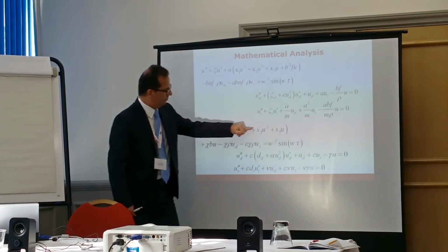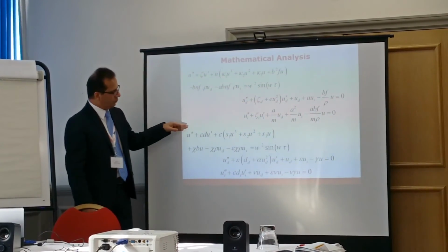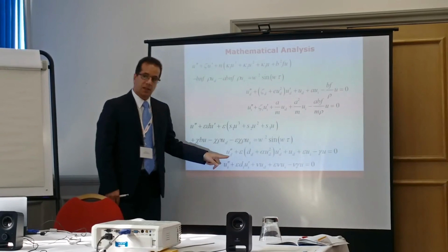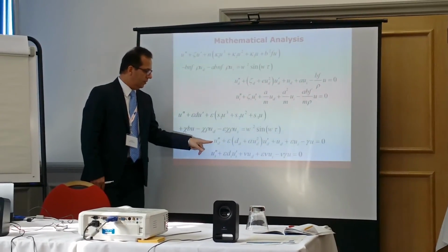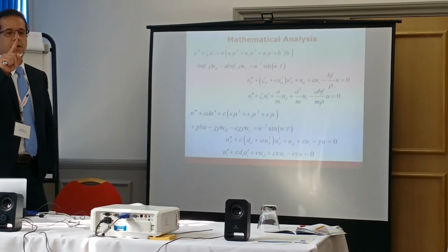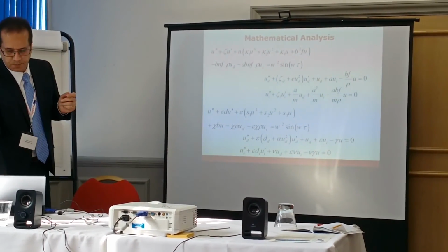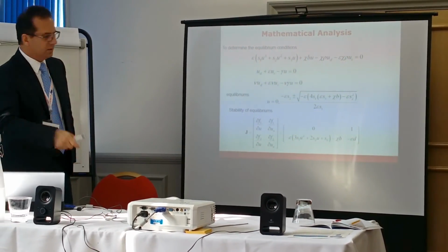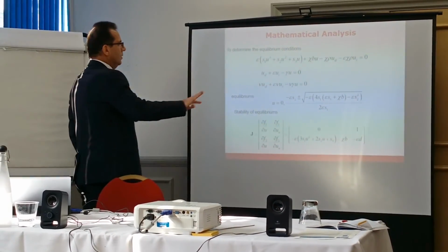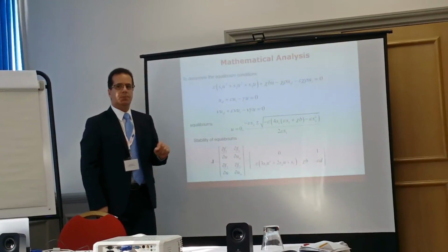One of them here in two lines, which is the displacement of the actual engine. UD is the decoupler motion, and UI is the inertia track. Inertia track is the mass of the fluid that is going through the tube. Three equations, and frequency analysis goes there,